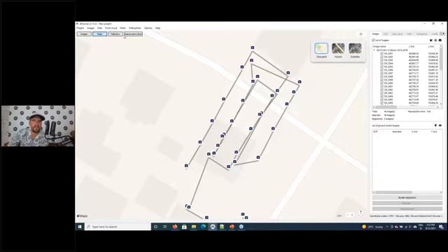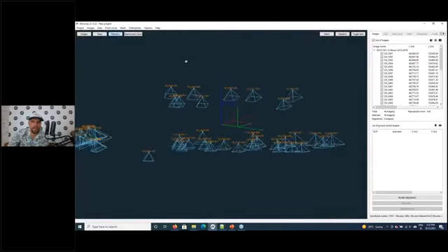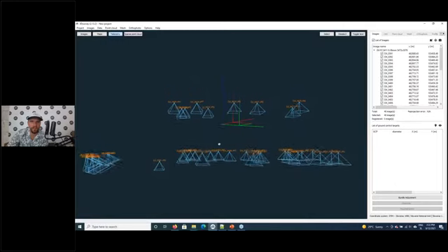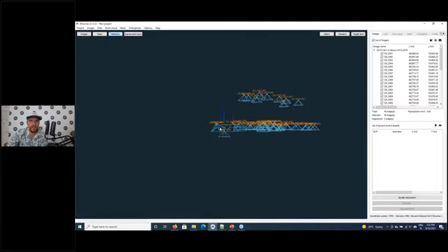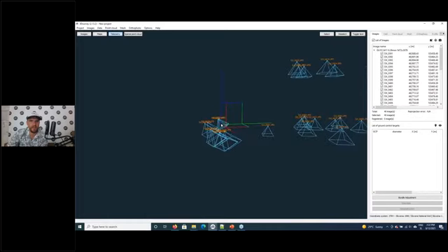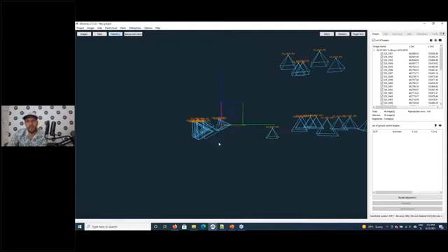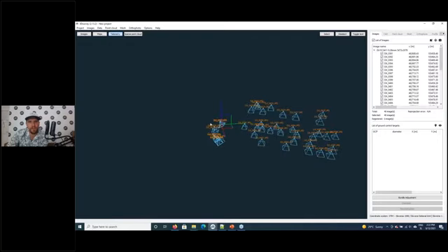At first I flew at 30 meters altitude, then I rose to 50 meters, and then in the end I also added some images recorded at a 60-degree angle. If the Mavic had waypoint navigation mode, I would probably also add a whole orbit, but because it wasn't there, I just added a few images, and a few are actually enough.